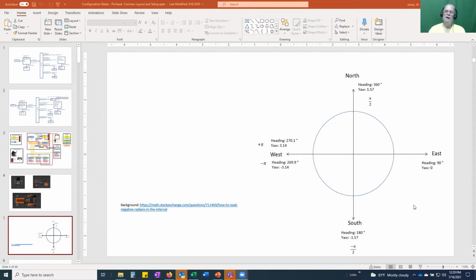So I modified it. Matt had it set up so that if the values coming in were NaN values, then that's invalid data. And he may have had to hack the NMEA Navsat driver to create NaN values in the first place. But I'm getting velocity directly out of that now. And I just say if velocity is less than 1/10 of a meter per second, use the latched value. If it's greater than that, pass the value through. And that does appear to work, but I still got a few little noise glitches on that.